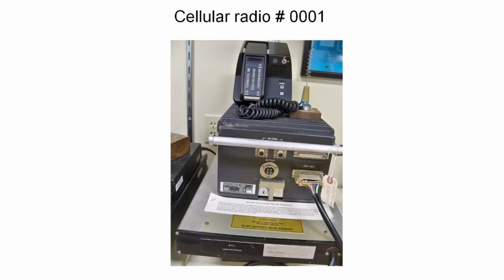One of the things that AT&T was worried about was that at 800 megahertz, in the cities with reflections from the buildings, there could be severe flutter or picket fencing effect from reflections. So they wanted to run space diversity with these mobiles. The problem was that non-radio people don't like antennas on their cars for some reason, let alone two. And after the tests were done, they decided that picket fencing was not as severe as they were afraid might happen. And so they deleted the option for space diversity on the mobiles, but the base stations still use space